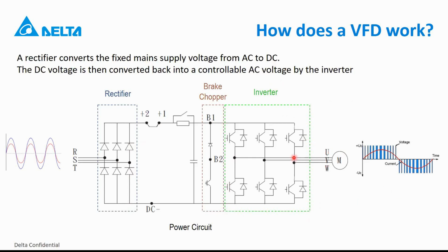Now, the sequence in which the IGBTs of the drive open will determine the frequency that the motor sees. The duration, so how long the IGBTs are open, the duty cycle, will determine the voltage that the motor sees.